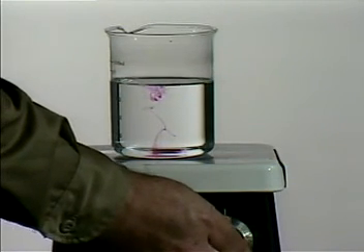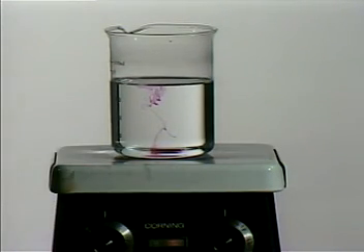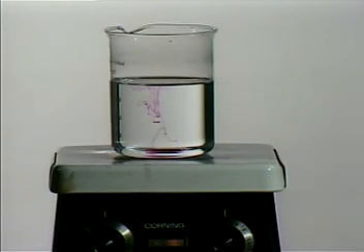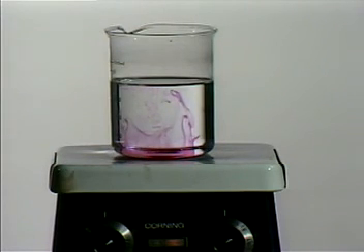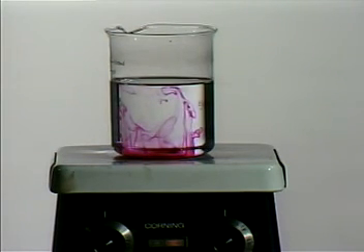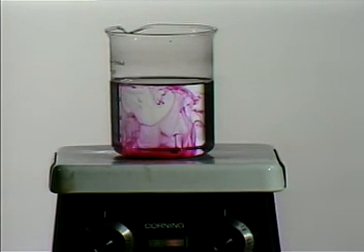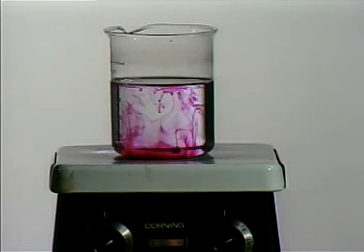When heat is applied to the container, the water that's closest to the bottom of the container is heated first. As the temperature of the water near the bottom increases, that water becomes lighter or less dense, and it moves upward in the container. At the same time, the water near the top of the container, which is cooler and heavier or denser than the warmer water, moves toward the bottom of the container. This is what happens during natural convection.